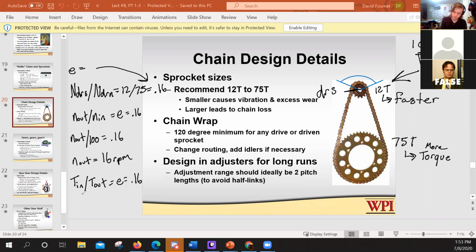So if our torque in is 10 inch-pounds, wait, I thought that our torque was 12 instead in D5. No, okay, that is a good distinction to make. One second. Write torque out here. This number here is the teeth, okay? So this says 12 teeth, 75 teeth, okay?